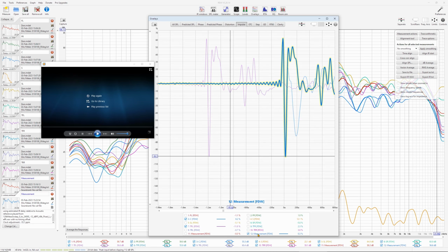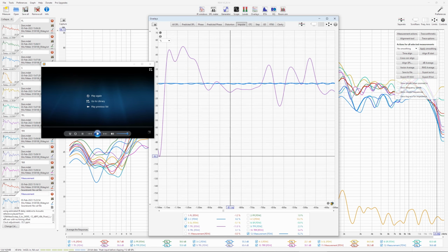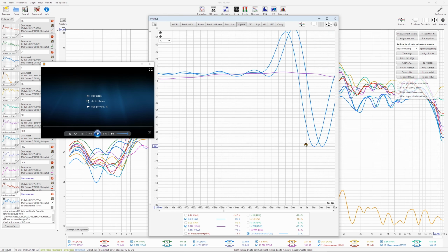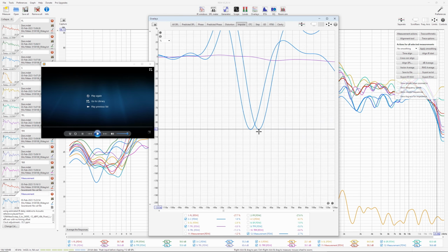Here is the top front left measurement, right on top of center. When you do this way, you will almost instantly get them right. As you see, the difference is 0.3 centimeters, which we cannot change. You can't change this better than 3-4 centimeters. Although in the receiver settings, it looks like it is 1 centimeter accurate. It's not, as I have mentioned in my previous videos many times before.